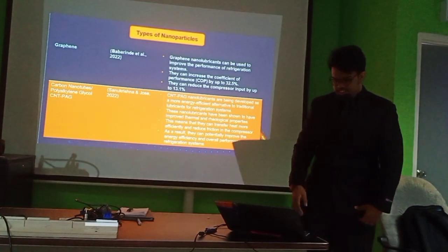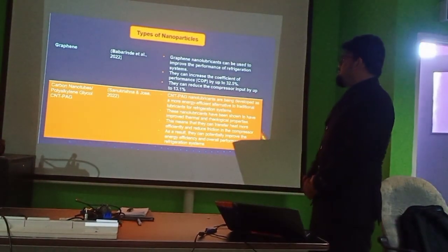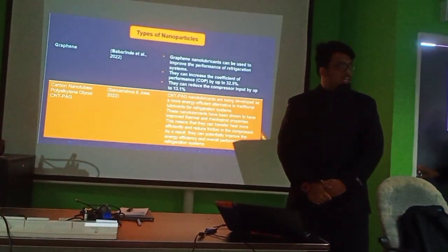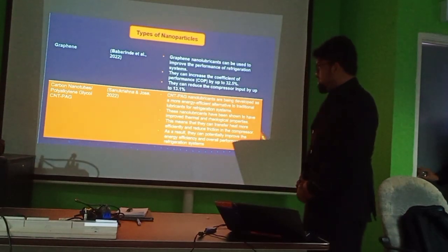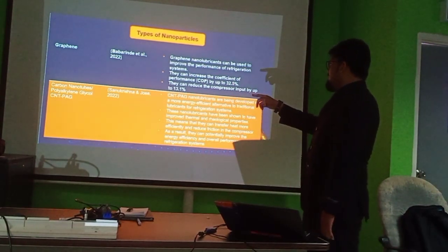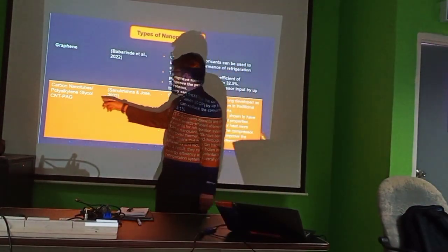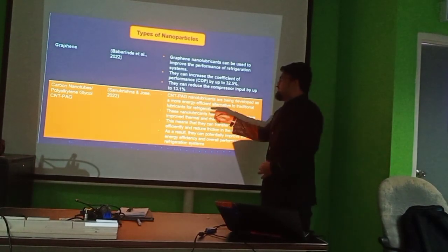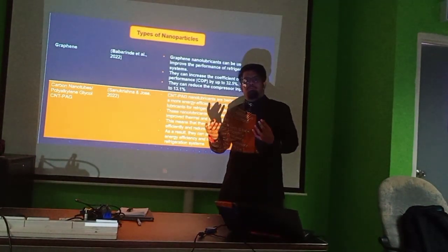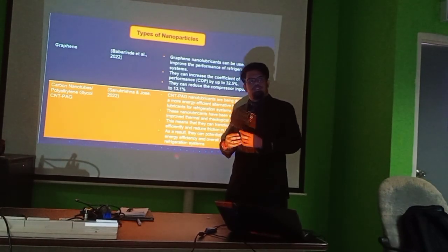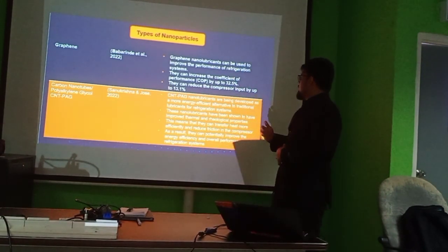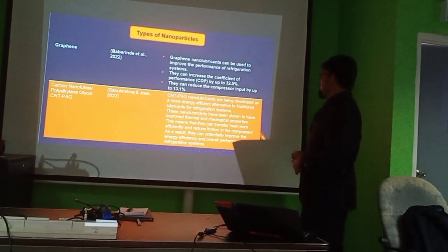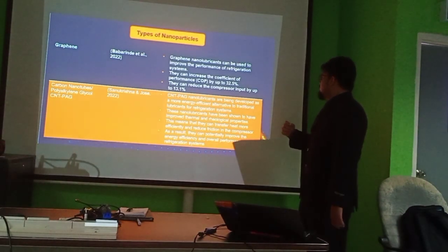Okay, next. Carbon nanotube and polyalkyl glycol, CNTPAG. In this journal, they use this type, carbon nanotube and polyalkyl glycol, as the nanolubricant, but this type is a powder, not a fluid. But the concept is the same. It is a more energy efficient alternative to traditional lubricant for refrigeration system.